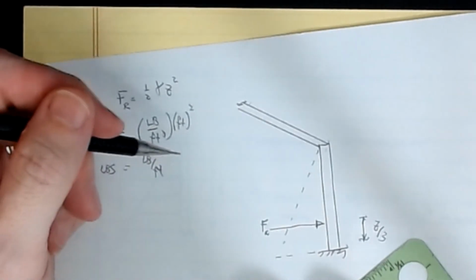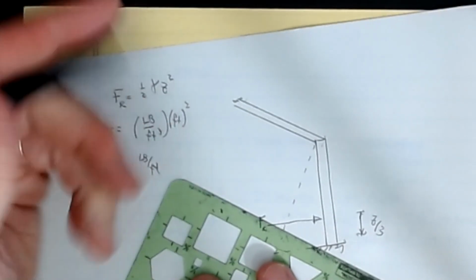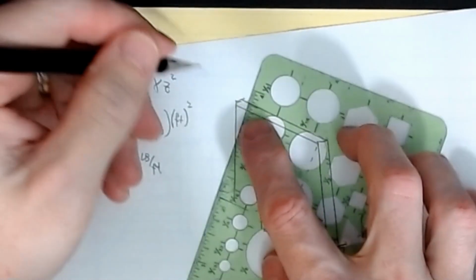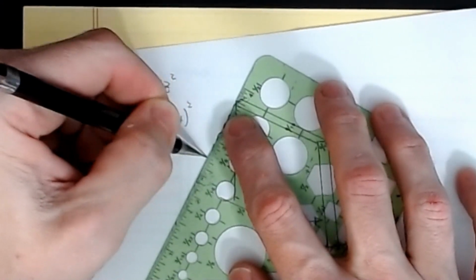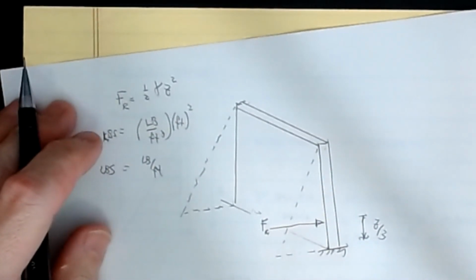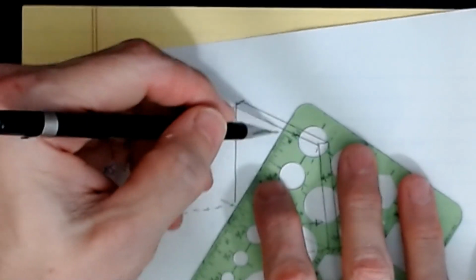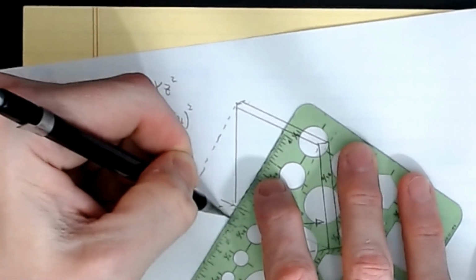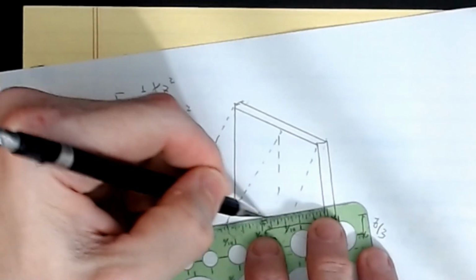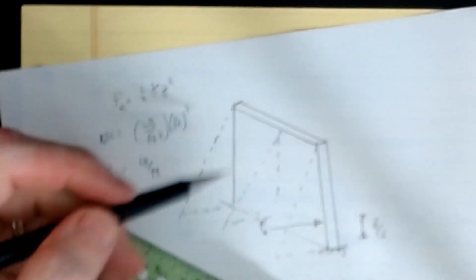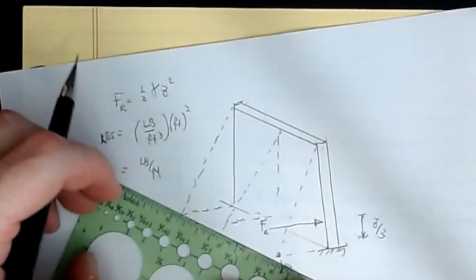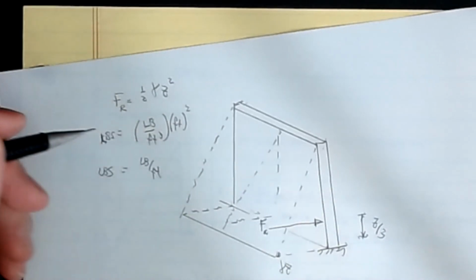If I go back and get our wall laid in here, on this back face you would also have a pressure profile of a triangle, and at every point in between, all has the same pressure profile, where this point is gamma times z.